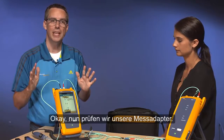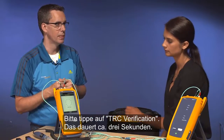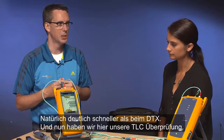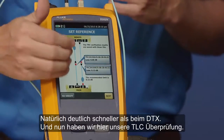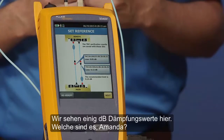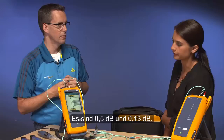Okay, let's do our test reference cord verification. Go ahead and tap TRC verification. This takes about 3 seconds to do, certainly a lot quicker than that DTX. And we have here now our TRC verifications, and we got a couple of dB loss values on there. What are they, Amanda? They are 0.05 and 0.13.